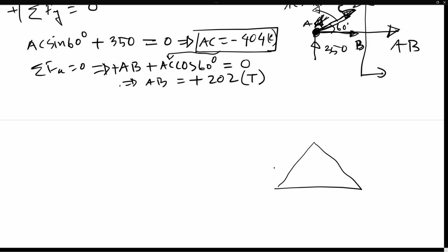So for this A, C, B, here we got 350, in this case, here we got 350. So that's 700 pound coming from the top. So these are the reactions, and the internal force by the AC member is compression, which is acting to AC.